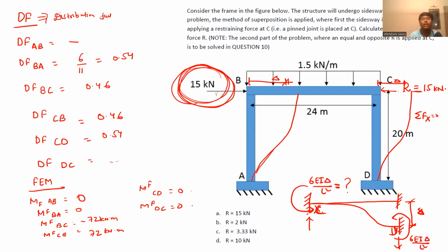Yes, sir. In displacement methods, your unknowns are displacements. After getting your unknowns, can you analyze your complete structure or not? Yes, sir. You can find movement, reaction, everything. Similarly, in the force method, your unknowns are forces. Once you are done with forces, can't you find deflections? You can use any method: conjugate beam, double integration, moment area method, any method you can use.